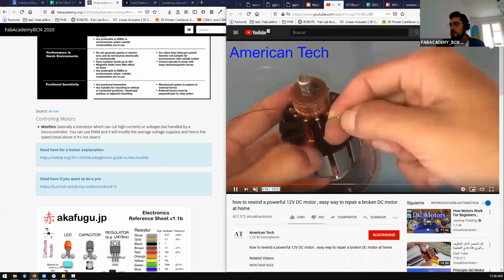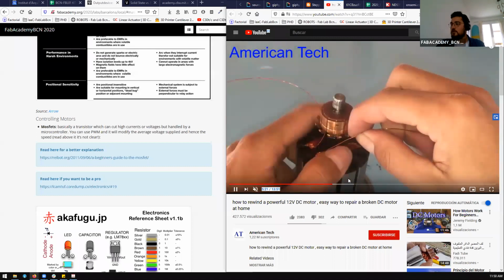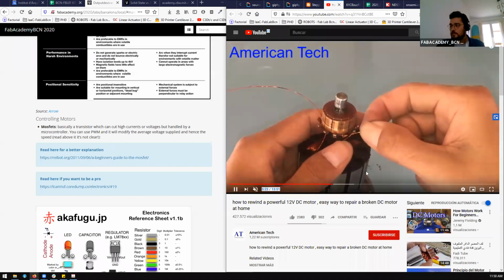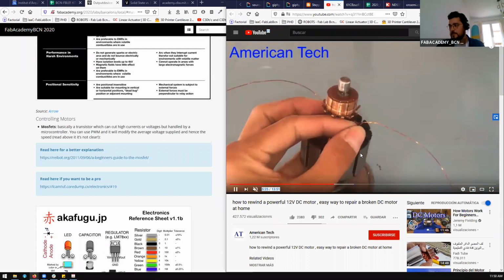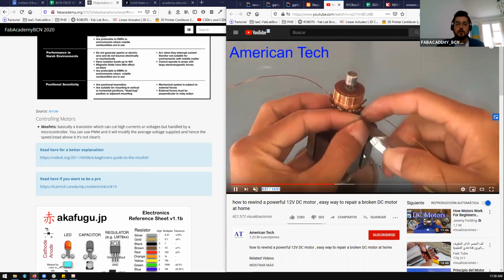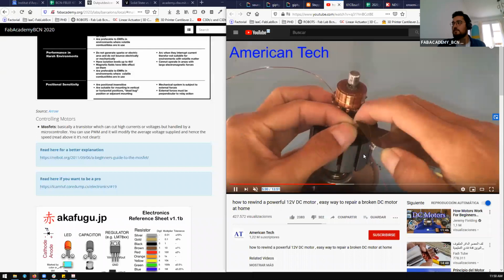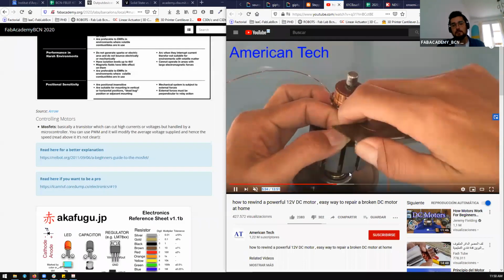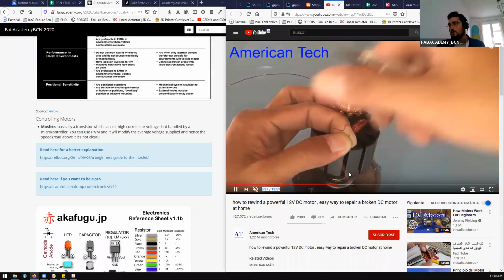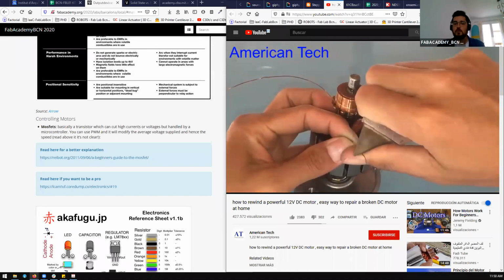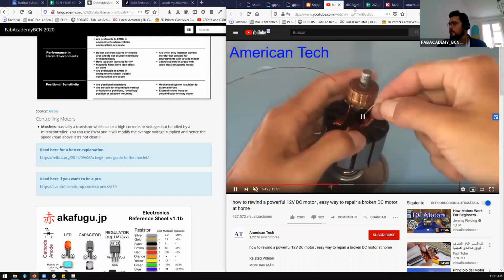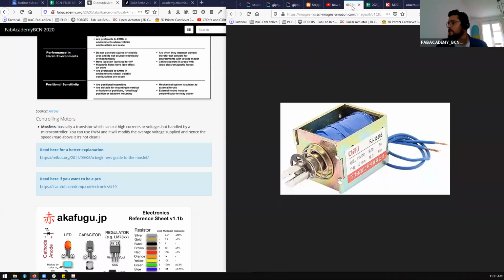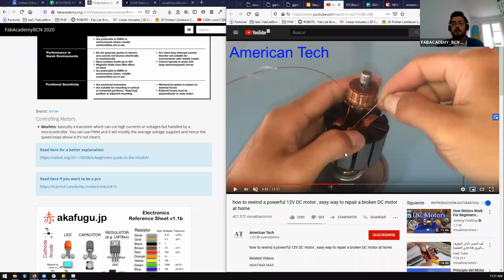And this is actually one of the definitions of motors: the number of poles, that is the amount of wraps that you can do, and the number of turns. So actually a motor is defined by the number of turns and the number of poles. More poles usually means higher speed, more turns also means lower voltage. Something that you don't need to be crazy about, but it's important when you choose a DC motor or brushless motor, that we will see later.